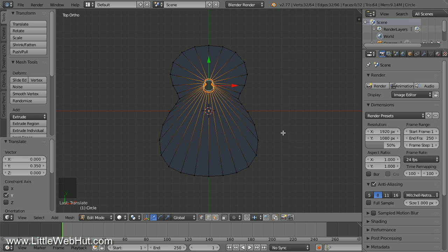Now add a face inside the vertices by pressing F. Later we're going to be adding a Subdivision Surface modifier. So to keep this surface flat, we're going to be adding some more geometry by adding loop cuts. Loop cuts are done in 2 steps. First, the edges that will be cut are selected. Then the loop is slid into position.